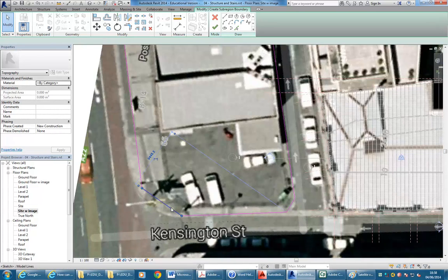Oh yeah, so here, we want that to be a rounded edge, so I'm going to delete this segment in between, and then using fillet arc, which is a draw tool, if you don't know it, fillet arc there. You can choose these two lines, and then just put a radius in between them.